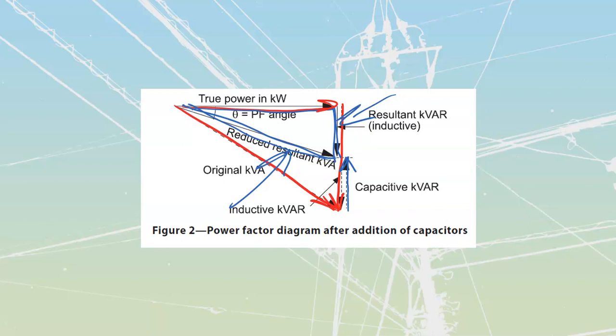The best method would be to have a combination of individual units and large banks. Stick a centralized large bank to deal with any small fluctuations and the thousands and thousands of tiny loads that you have around your plant, but then put in large individual capacitors on your larger inductive loads, things like gigantic motors that you might have, etc.